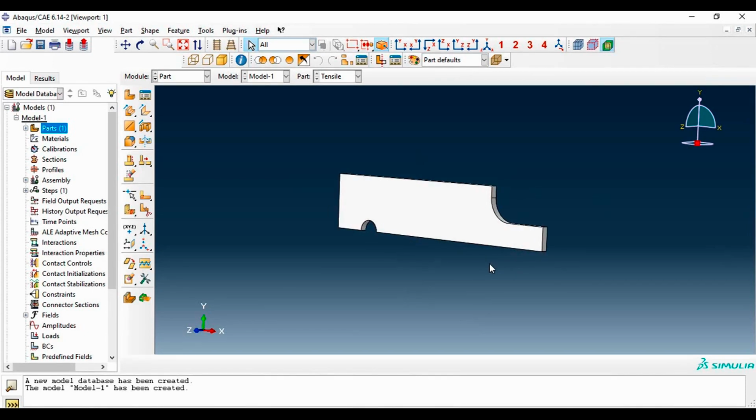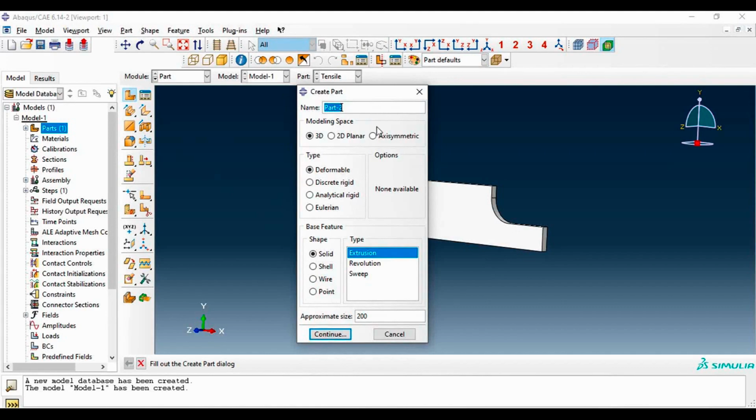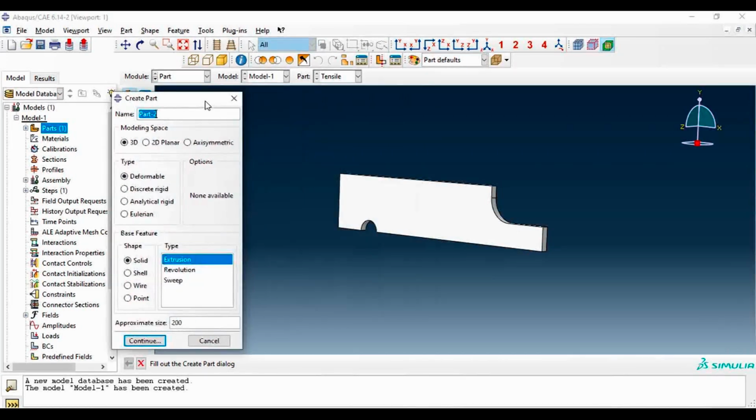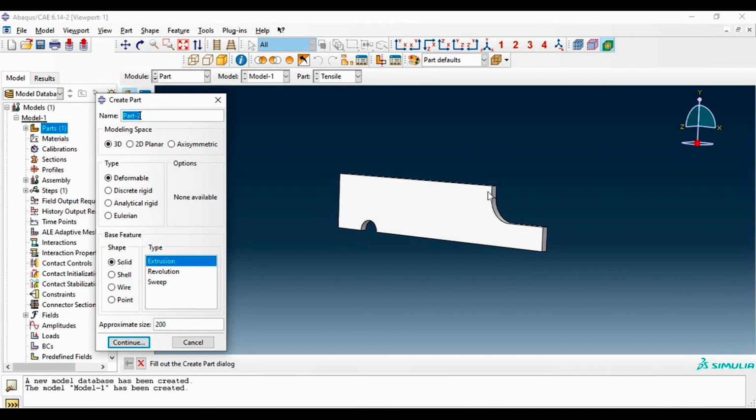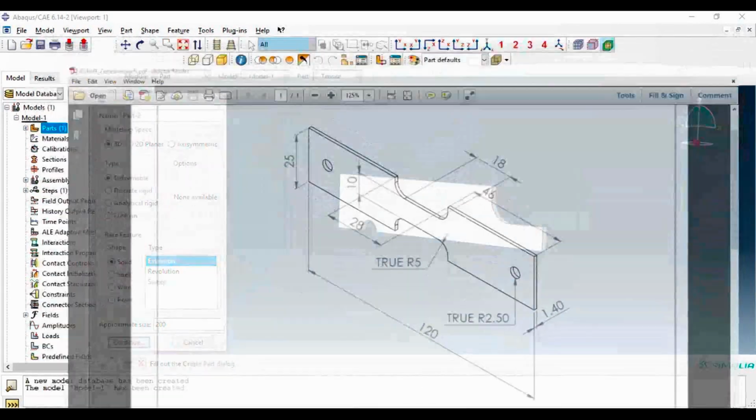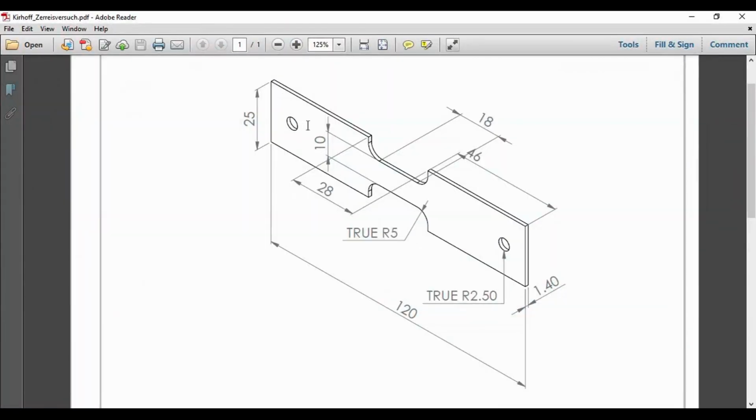as a 3D. You can also use this drawing, and then by extrusion, it means you just need to draw this plane. As you can see the dimension here, just choose the 1/4 of this. By the way, I just remembered that the distance between the center of this circle to here is 10 millimeter. So remember this. From the center of this, it is my mistake.